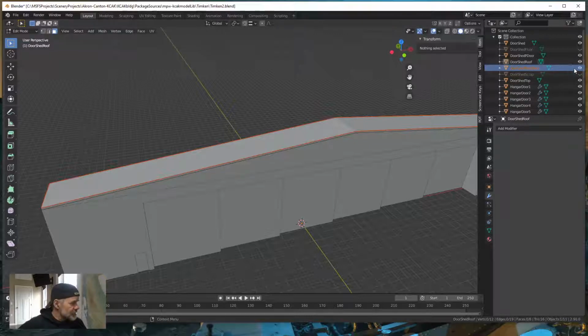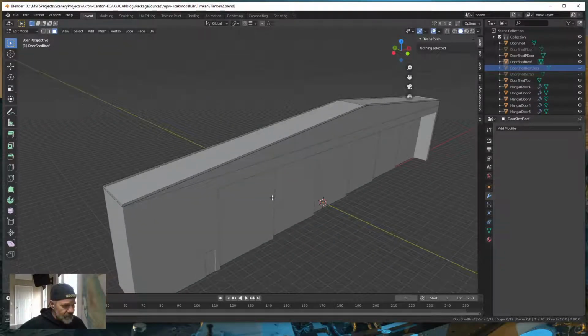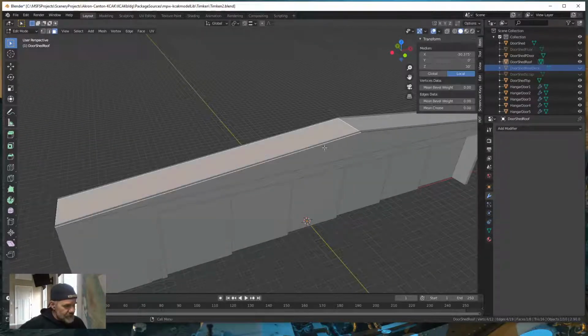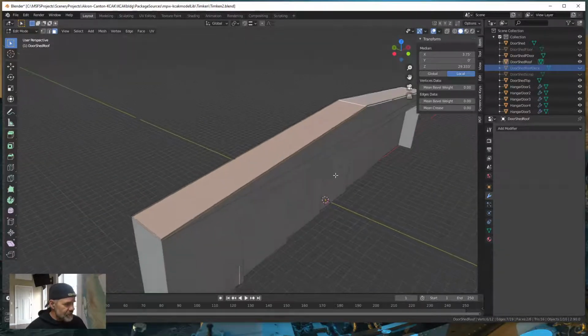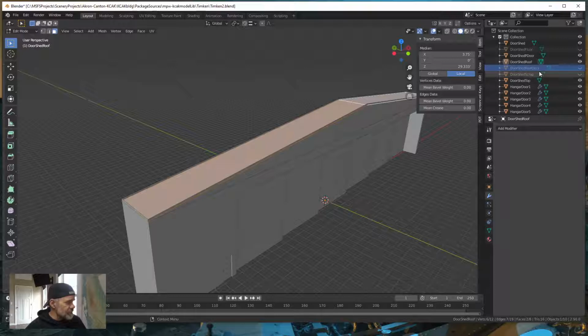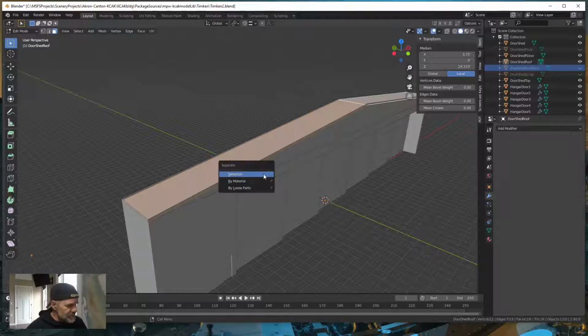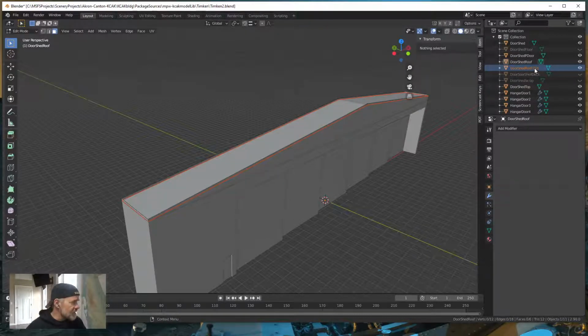Okay, so if I turn off the roof deck, now these two polygons that are underneath those are the roof ceiling. Okay, so I'm going to hit P, make a new selection, and I'm going to call that the roof ceiling. And there's a reason why I do this,